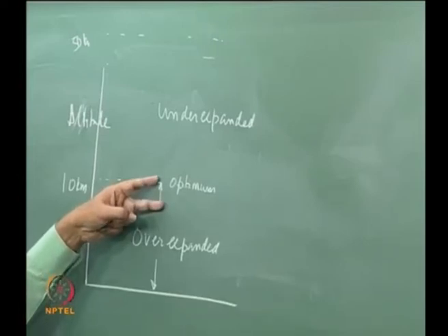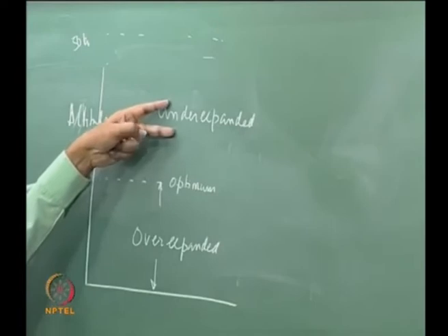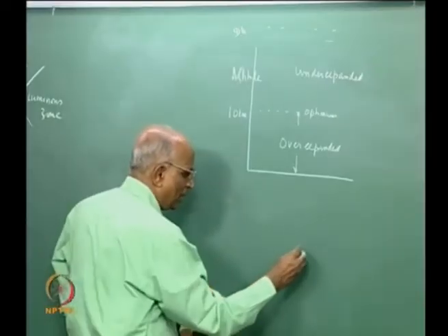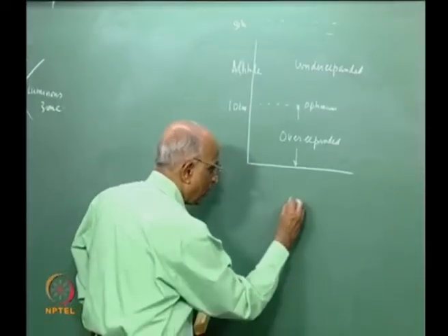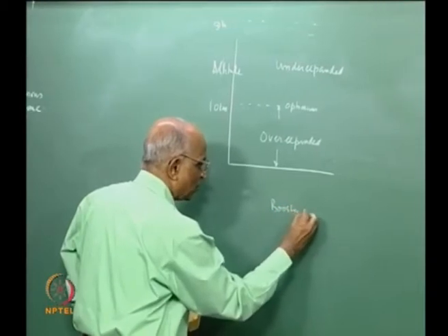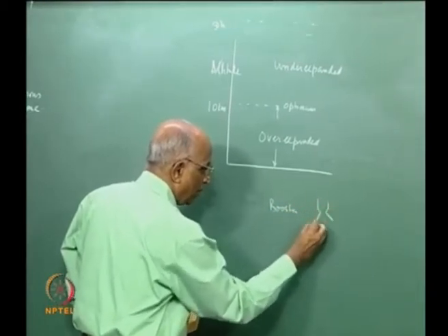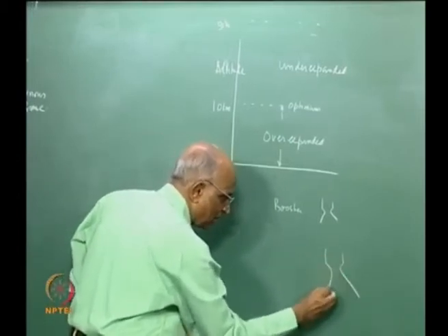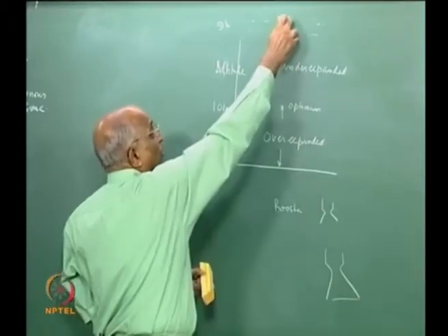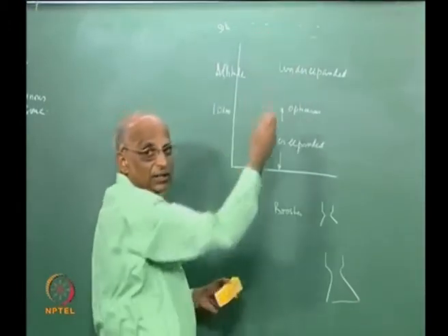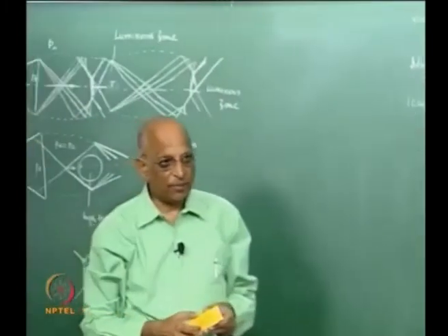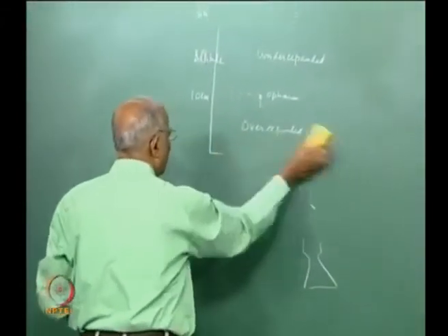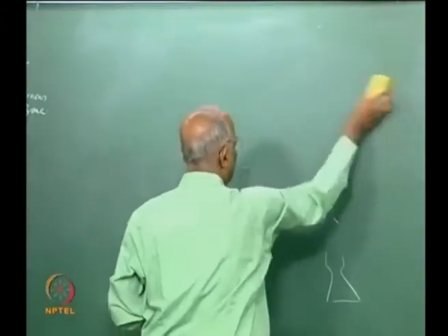it is always that a given nozzle operates either in an under expanded mode or over expanded mode, but we try to decrease it. And as you would have seen in the earlier figures, a booster stage has a small nozzle, whereas if the rocket is going to fire at high altitude, I will design it with a larger nozzle such that the optimum shifts to the higher altitude, and this is something which we have to keep in mind. I think something more we must remember while we are talking of under expanded and over expanded nozzles.